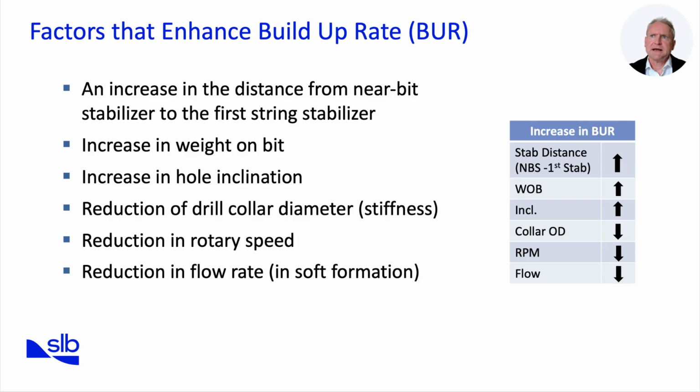Now, let's look at the key factors that drive the build-up rate, or BUR, of a rotary BHA. The build rate is essentially the rate at which the wellbore angle increases per unit of depth, and it is controlled by both the BHA design and drilling parameters. The first significant factor is the distance between the near bit stabilizer and the first string stabilizer. Extending this distance magnifies the fulcrum effect, which generates a stronger side force at the bit and increases BUR.